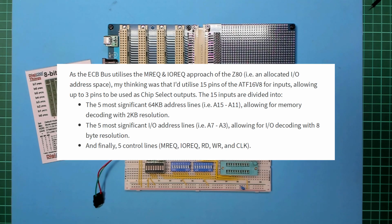The 15 inputs are divided into the 5 most significant 64K address lines, i.e. A15 to A11, allowing for memory decoding with 2K resolution, the 5 most significant I/O address lines, i.e. A7 to A3, allowing for I/O decoding with 8-byte resolution. And finally, 5 control lines, memory request, I/O request, read, write, and the clock signal.